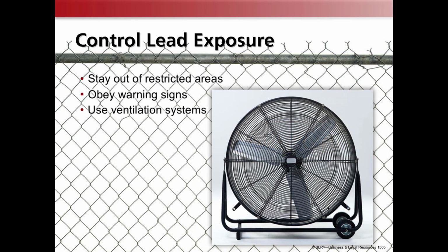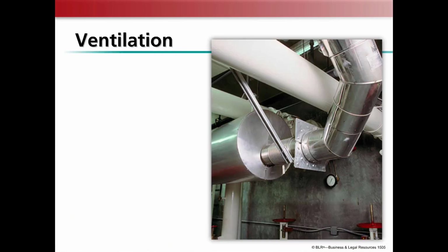Open doors and windows or use a fan that blows outdoors. At outdoor construction sites, large fans can blow dust away from the workers. Ventilation is one common protection against overexposure to airborne lead. Mechanical systems may be used with enclosures or containment situations. Remember, lead cannot be vented outside one work area to another area. Lead dust and fumes must be captured in some type of collection system.